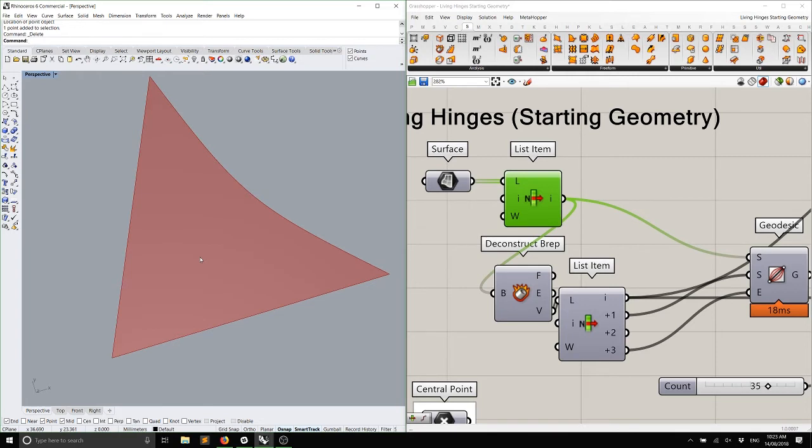So, if I were to now take this object, I'm just going to draw it, and I would then put this onto a piece of plywood. I know by default, we're going to just lay this out on a piece of plywood so that it fits, yeah? We've got our sheet of plywood, we lay it out, we just rotate it however we want so it fits, yeah? But if our plywood grain is traveling in this direction, we're actually going to make something that's counterintuitive to what we're going to construct.